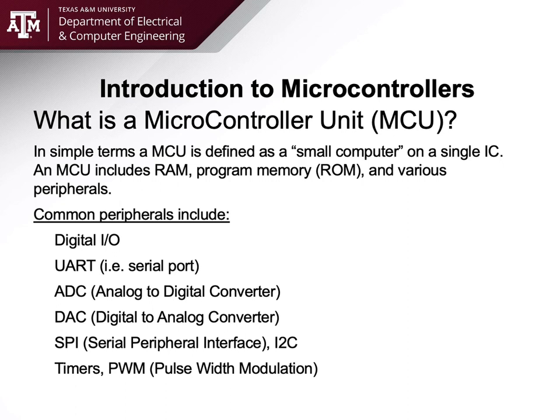And of course, if you had 250 microseconds on and 750 microseconds off, it would be 25%. That is highly used in heater control, servo control, all sorts of mechanisms. The LEDs in the backlight of your laptop and your smartphone are typically controlled using some form of pulse width modulation. You also use timers for timing events.